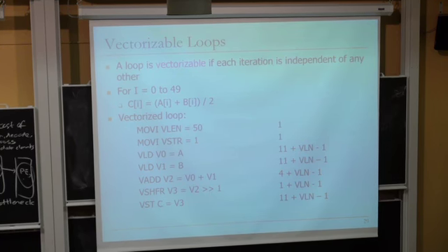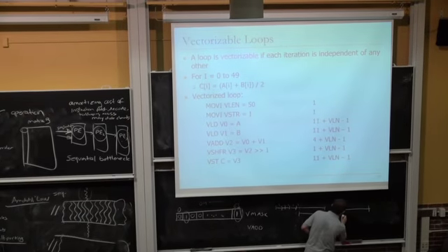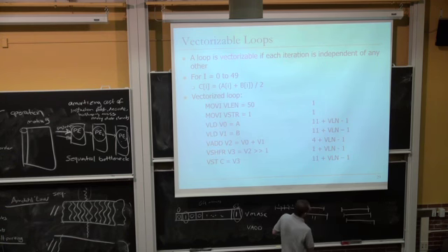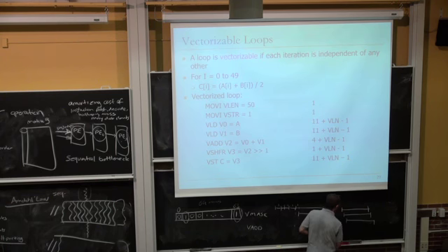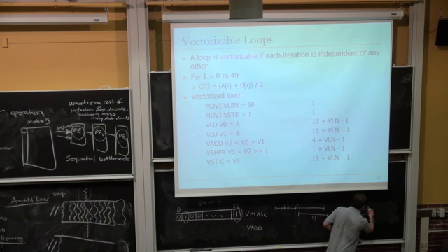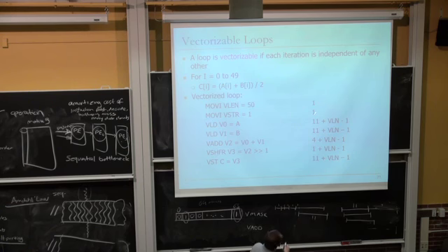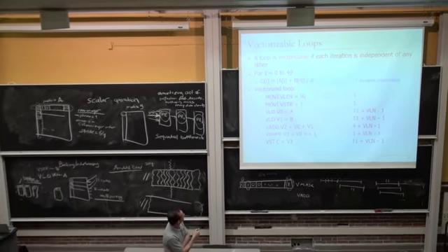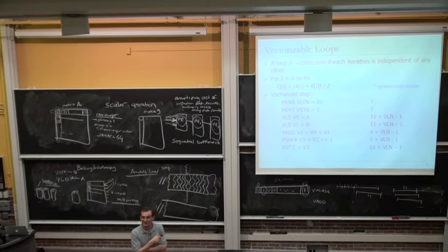So you start the first access here, and then the next access in the next cycle, the next access in the next cycle. So essentially, you have vector length number of accesses, and the first one takes 11, and you finish every other access 49 more cycles later. You finish the first access at the end of the 11th cycle, and after 49 cycles, you finish all of the other accesses, right? So that's how you can compute this. Okay, before we go into how we can optimize this, if you look at this, this takes 7 dynamic instructions, right? There's no looping here.